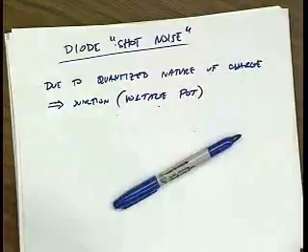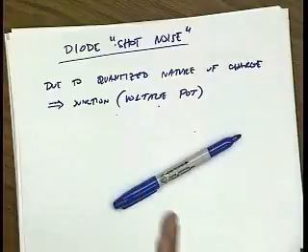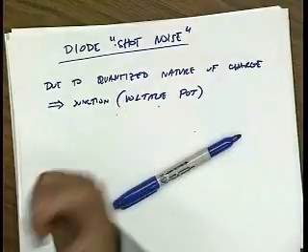And these carriers are not arriving uniformly. They're arriving randomly. It's actually a Poisson process, a random arrival time. So these charge carriers arrive randomly, and every time they arrive, you get a little delta spike of current. If they arrived uniformly, then when we looked at the spectrum, you would expect to see spectral peaks at all harmonics of the period of arrival.